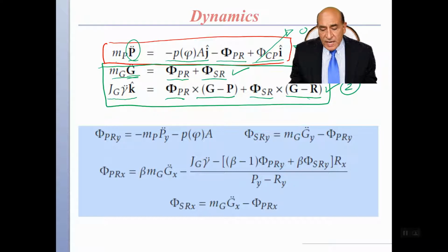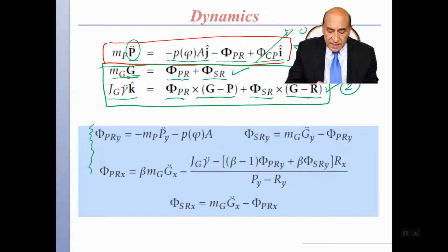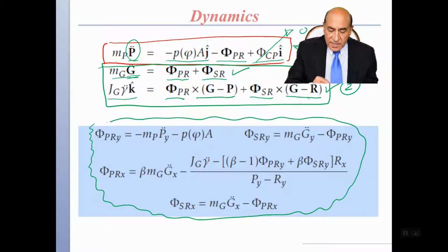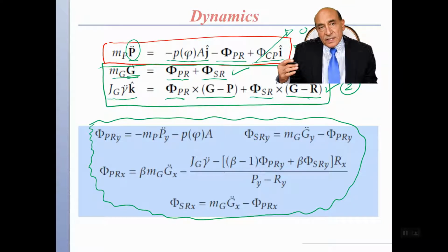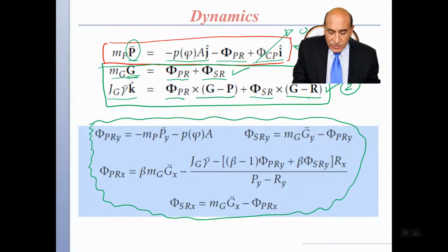And we have a task for this project, and the task is to derive the equations for the reactions on the left and the reactions on the right, that is, from the cylinder, from the piston on the rod, and from the crankshaft on the rod. These are four forces in X and Y, and we want to write the forces in terms of the driving